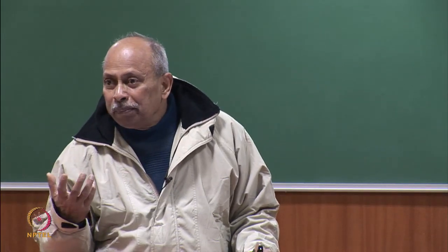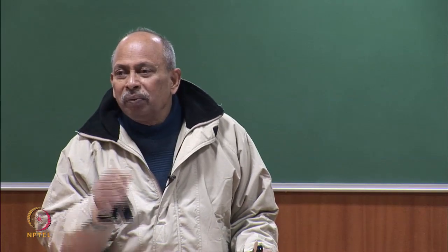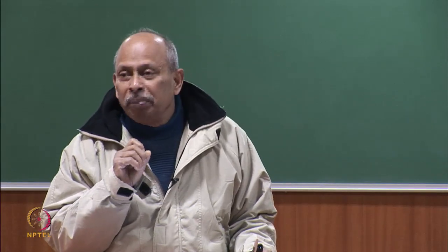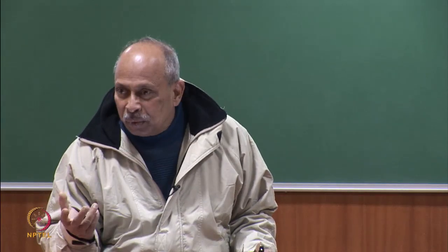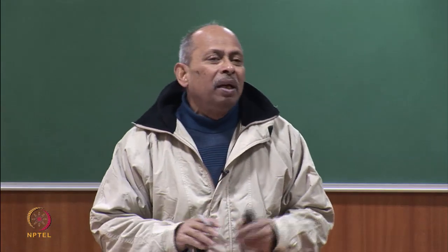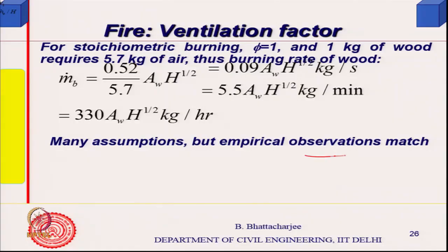Approximately you can estimate the fire load, and then use this formula to find out that maximum the fire could have been this if it was uninterrupted, no human intervention. But had there been human intervention, obviously firefighting etc., they would have reduced it. So, there are many assumptions, a lot of assumptions.